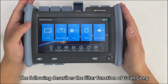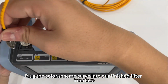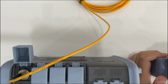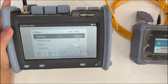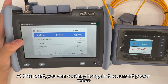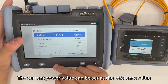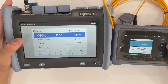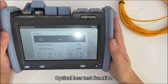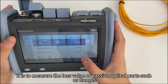The following describes the optical filter function. Click on the optical filter. Plug the light source into our optical filter interface. Find our light source. Switch to the corresponding wavelength. At this point, you can see the change in the current power value. Click Reference Value. The current power value can be set as the reference value. Click to switch the wavelengths. Continuing wavelengths can be replaced. Optical loss test function. It is to measure the loss value at passive optical parts such as flanges.